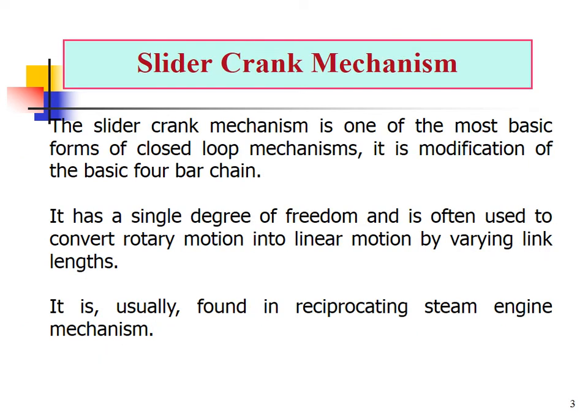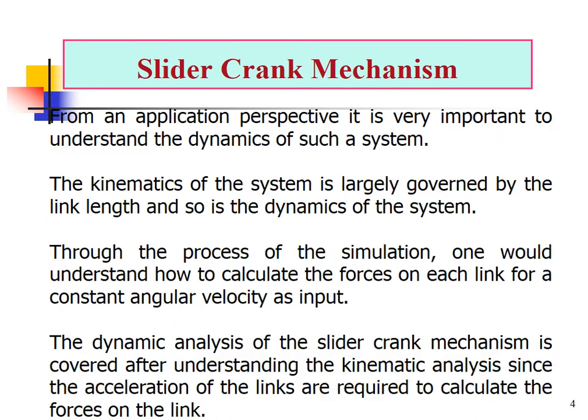The slider crank mechanism is one of the most basic forms of closed loop mechanism. It is a modification of the basic 4-bar chain. It has a single degree of freedom and is often used to convert rotary motion into linear motion by varying the link lengths. It is usually found in reciprocating steam engines.